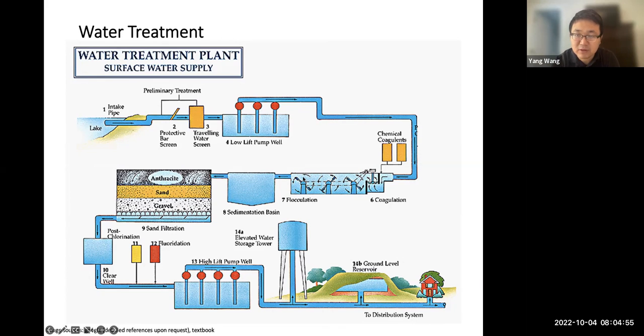At the same time, you need a longer residence time. So that's why the flocculator has a larger volume, right? So you need a longer time for these particles to gradually collide with each other and then form those larger particles so that they can settle down, right? After they settle down, they can go into the sedimentation basin to let the particles further get removed based on gravity.